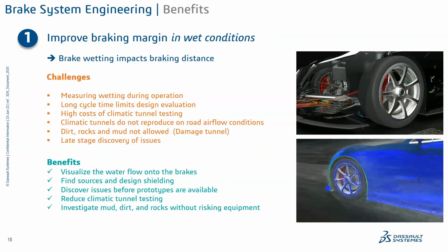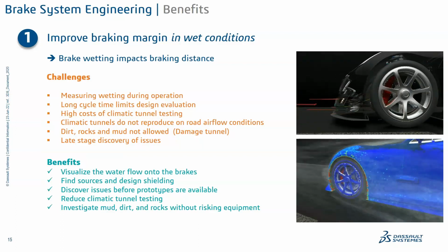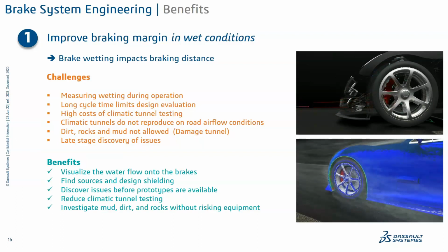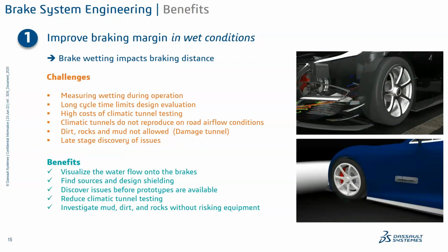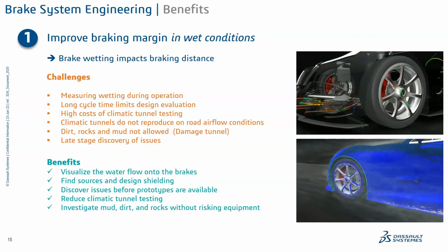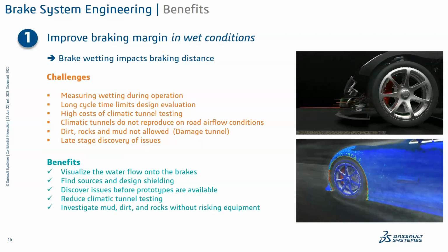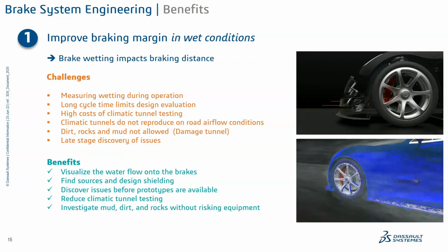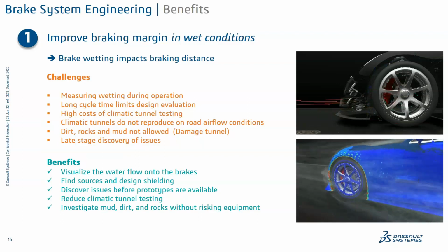Braking margins should also work in wet conditions. Again, there are certain challenges when you're designing the brakes in the labs. You have certain restrictions. You cannot have a wet conditioned lab. Nowadays, most of the customers or brake manufacturers are using climatic tunnel testing with UV dyes, which again doesn't provide a closer insight into what exactly is happening inside the system.